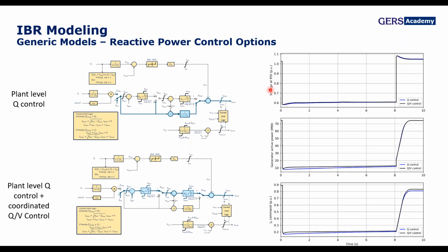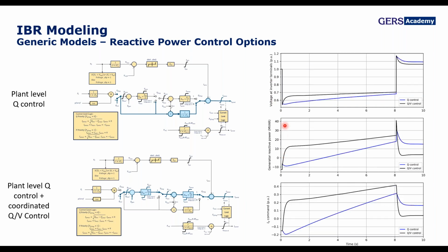In terms of reactive power they are kind of similar, but in terms of voltage, you'll see that the second one is faster. The black one reaches some specific points faster than the other one. I wouldn't say that one is better than the other, but it depends on transmission planning guidelines, the point at which the inverter will be connected, and the strategy that the manufacturer uses for its product.